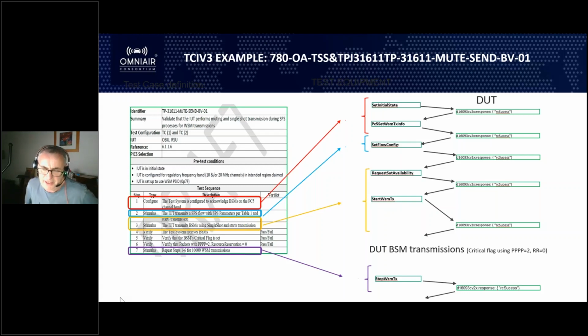Now, what I've missed out intentionally here, and we can maybe touch on it later, is there is optionally a bunch of messages that can be used to configure the DUT in terms of the side-link configuration message. This is another new addition for TCIv3, which allows the ASN.1 encoded UE pair RRC message, lots of acronyms there, apologies, a bunch of hex essentially, that can be configured and loaded down to a modem, which tells it which channel to use, which EARFCN, as it's called in cellular V2X, which bandwidth to use, and which selection of, say, resource blocks and various other physical layer parameters. Now, I've missed it off this particular test step because that would be probably done once at the beginning of the whole test regime. We can talk a little bit more of that later on.